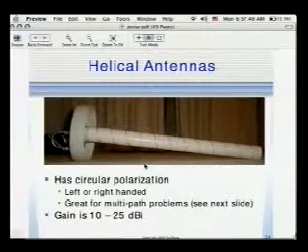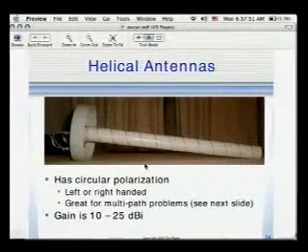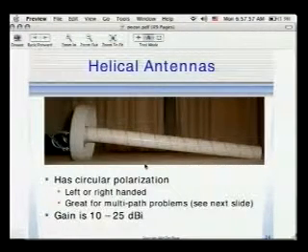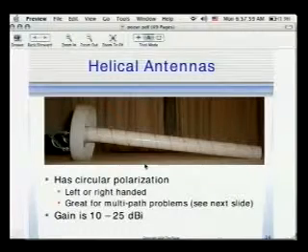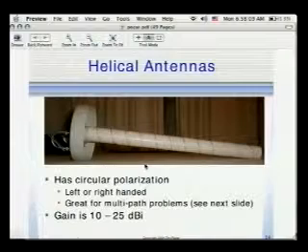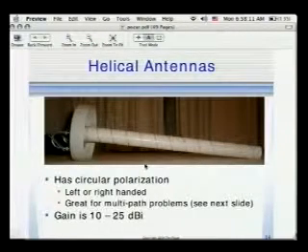Polarization is a good way of attenuating multipath, or of squeezing more radio signals into a particular band. For instance, with satellite reception, you may have a satellite way out there, and you use one polarization to pick up one signal and another polarization to pick up another signal that may be on the same frequency, located in the same direction. It works something like that for multipath.